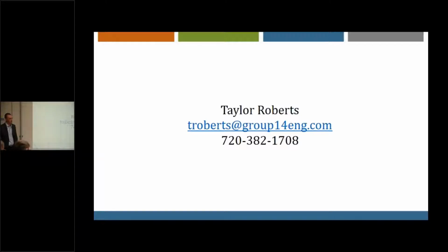I just have a question. It's a very specific question. Have you had success or have you tried modeling DOAS systems in OpenStudio? Yes. Hard size, hard size, hard size. Any air loop is going to want to autosize to meet all the loads in a zone. So to do a DOAS, you always need to be hard sizing all the flows so that it doesn't do that. Otherwise, you'll get crazy. You'll have a DOAS to a 4-pipe or whatever, and it will try to meet all those loads without the 4-pipe. That's just kind of how EnergyPlus works.